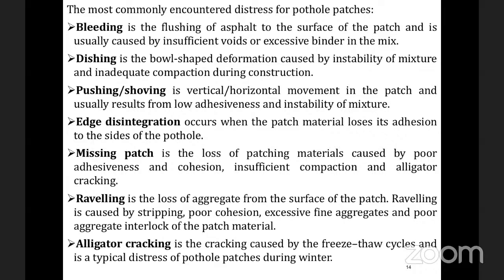Why does it happen? It happens due to instability of the mixture. The mix which we have done has low stability, then this happens. And if we have not given enough compaction, that is inadequate compaction. Next is pushing or shoving. It is nothing but a vertical or horizontal movement in the patch.